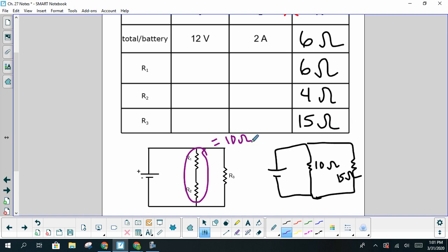Okay. And so then we take a little bit closer look at our circuit, and I notice that R1 and R2 share the 12 volt potential difference. So if I think about the red, the positive terminal of my battery being the high potential, I'm going to color that in red. That's going to represent my high potential. And then my low potential, or my ground, I'm going to color in blue. Notice my wires have all the same potential. There's no drop across there.